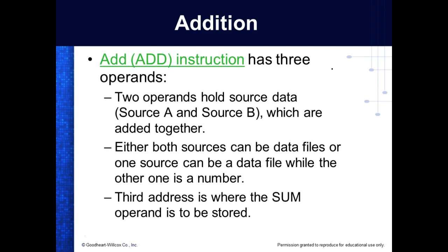A lot of y'all think what you're doing is storing information directly to the output. You're not. The PLC's taking care of that. What we're doing is storing those ones and zeros in a data file. And then when the PLC reads that, it reads those ones and zeros and decides what to do with them, right? The inputs, it'll bring in and use directly so it can process them. The output data file, it reads the ones and zeros and turns on the output ports that have a 1 in that data file, and it turns it off if it's got a 0. But it's a data file, guys.